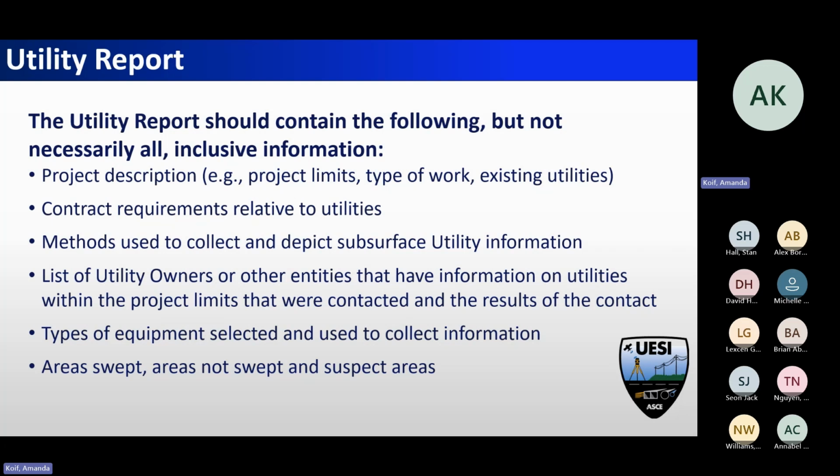Because depending on the type of pipe and cable locator that you use, which we have to document, some of them only work perpendicular, and there are some that will work if you're skewed a little bit or if the line's skewed. So which type you actually use to sweep with will determine how accurate that sweep could be. You could be off because you're skewed and using one that's perpendicular, or you could be better off if you're sweeping an area in a circle and you've got two that are omnidirectional. So it could be any different way to use that.